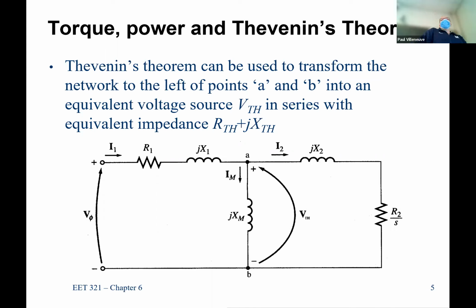So now we're going to expand a little bit. This is totally up to you. This approach of using Thevenin's theorem to calculate torque and power is a way if you're going to calculate it manually every time. If we use MATLAB, and the file I uploaded on Tuesday has all the information, you can just do brute force. You can do enough calculations to get accurate results. With Thevenin's theorem, you have some approximations to simplify things, but you get pretty good results nonetheless.